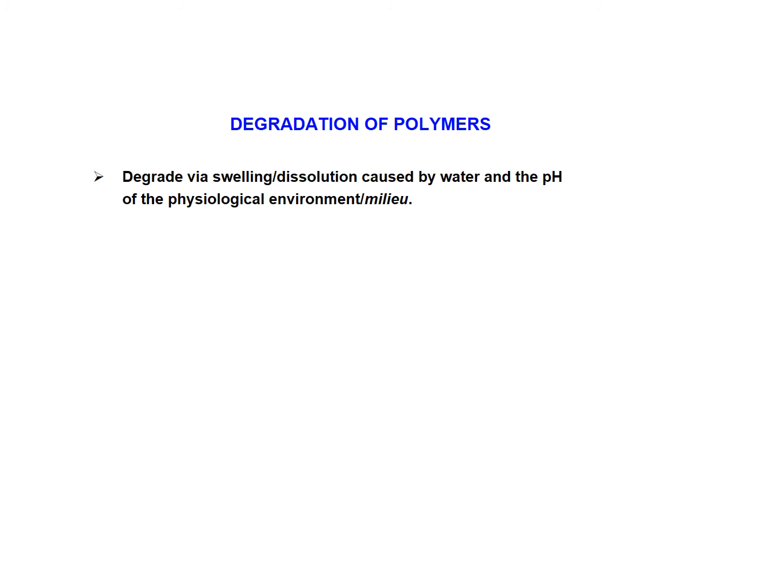Many implantable devices these days are composed of polymer materials. Degradation of polymers takes place via swelling because water infiltrates their structure, and in the water environment and the pH of the physiological milieu, they start swelling, and slowly but for sure that particular process can cause their degradation.